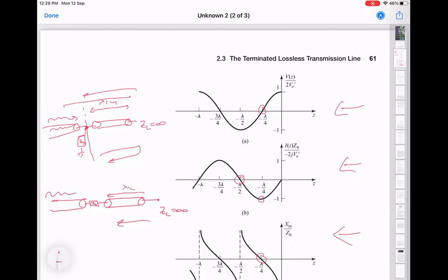So one good place to put them are in such locations, because at RF, at microwave frequencies, you will just not even see that connection. But at low frequency, at DC, it could perfectly pass a current through it.